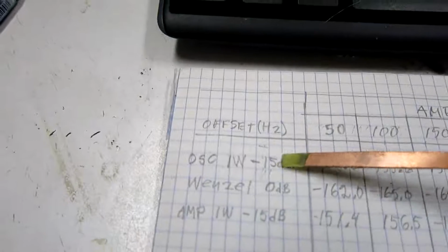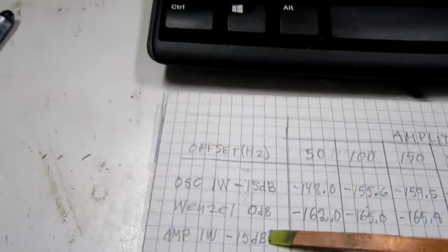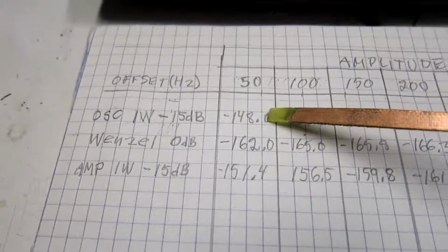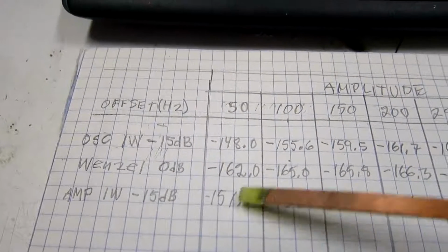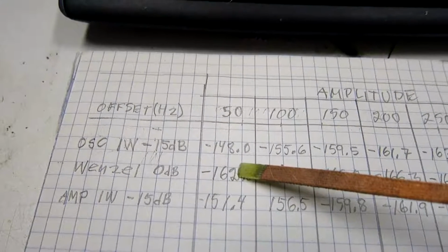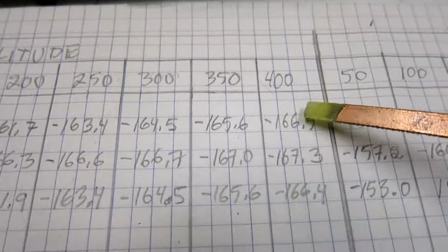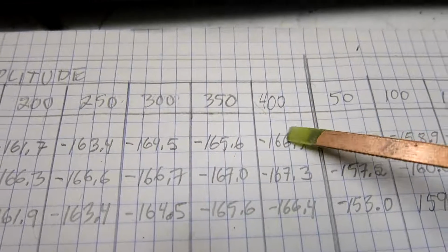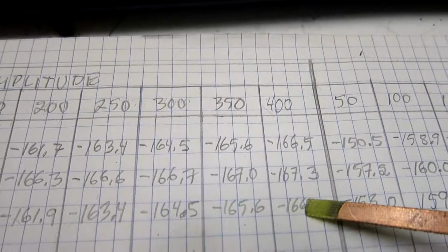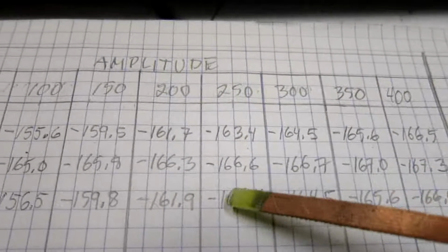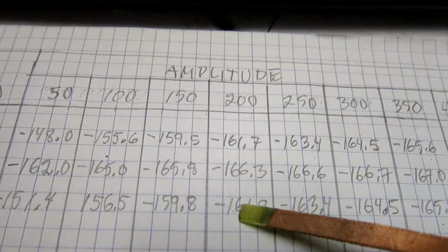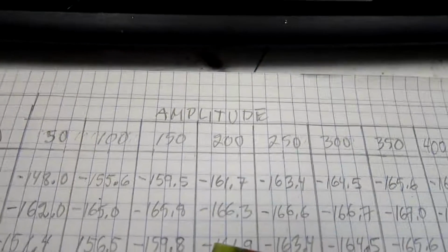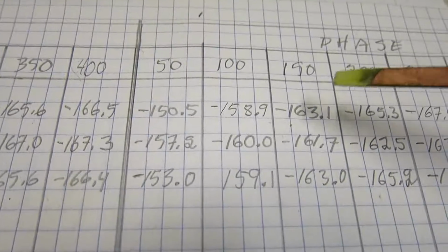As an oscillator or as an amplifier, at close range, the oscillator is more noisy than the amplifier, but the amplifier is much more noisy than the driving low noise oscillator. At wide separations, the amplifier output is the same, regardless whether it is an oscillator or an amplifier. And this is valid all the way to about 200 Hertz separation, maybe 150, for amplitude noise. For phase noise, it is similar.